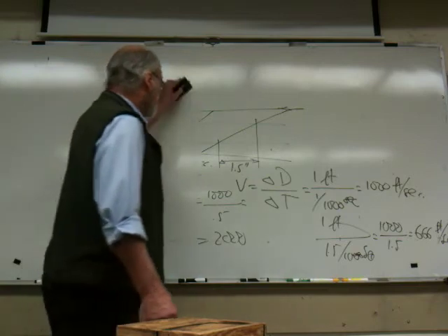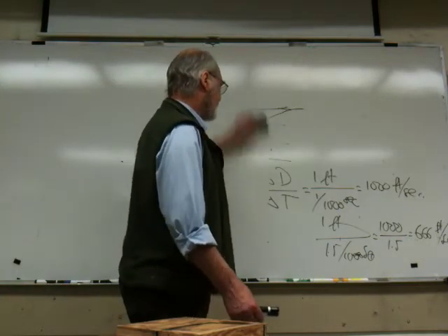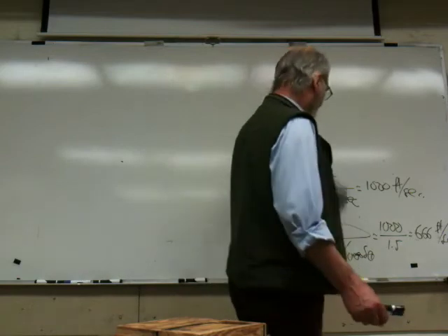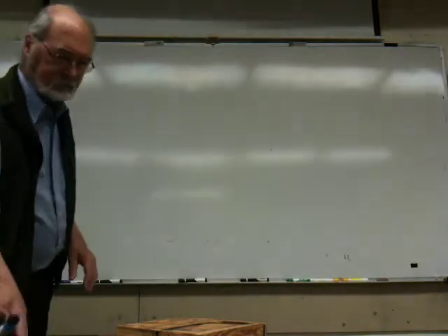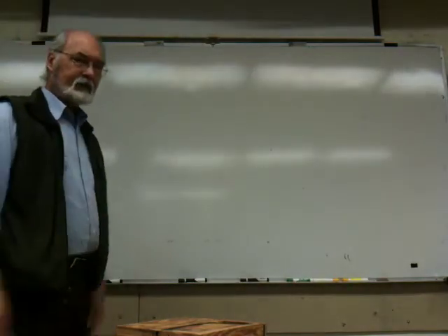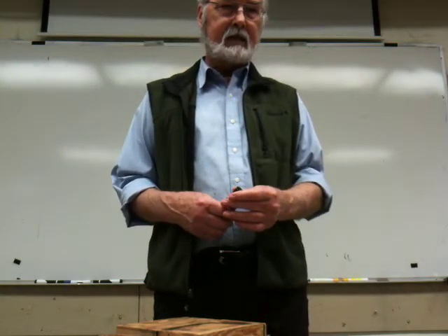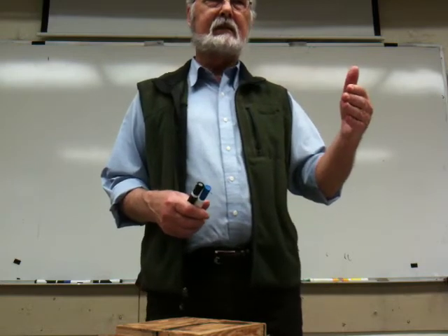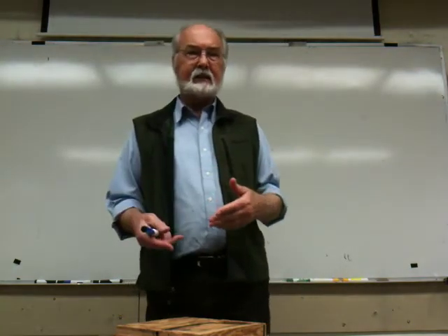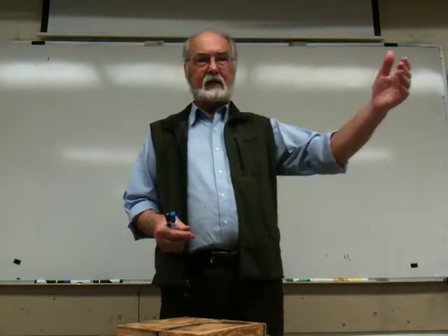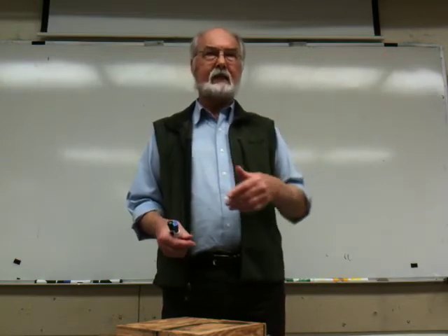The other one is to use something called a phototachometer. Car people use those, I think, but not quite as extensively. I'm not going to draw it. A phototachometer simply measures the time between light pulses that get to the photodetector. So it's kind of a light meter, and it looks out there. It says, well, I see a flash of light, and I see another flash of light. I can determine what the time between them is and give you a readout in RPM. I made one of those.